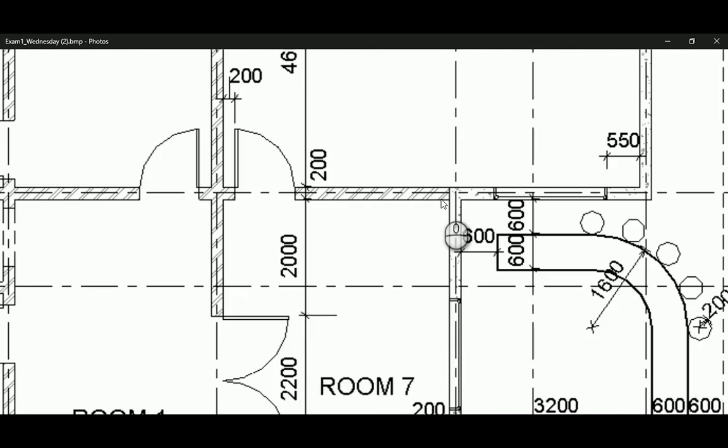Here the hatch, pay attention to the type of hatching you have. The hatch is here different. That means we need a separated layer for the partition. So that's the external walls. And if you didn't see that line and the hatch goes the same, that means we have the same wall type, but in here it's different.